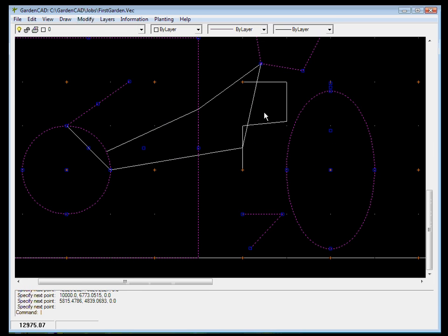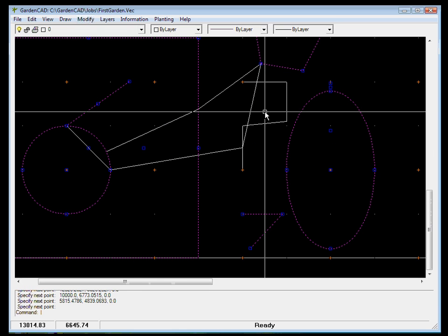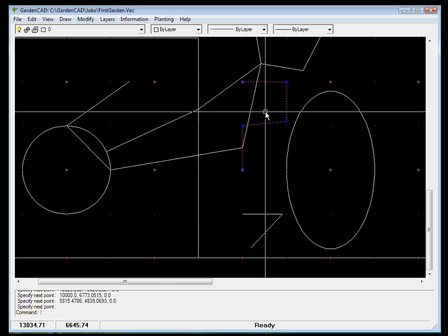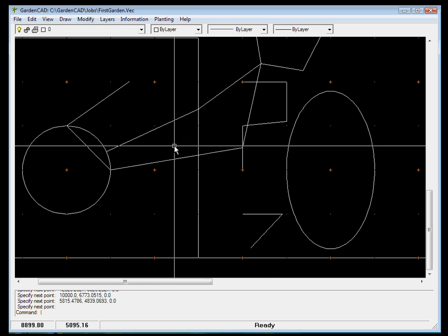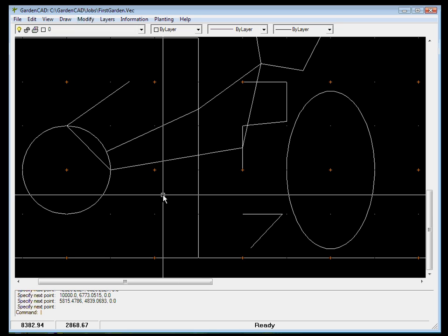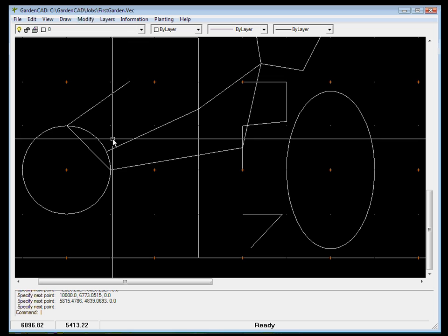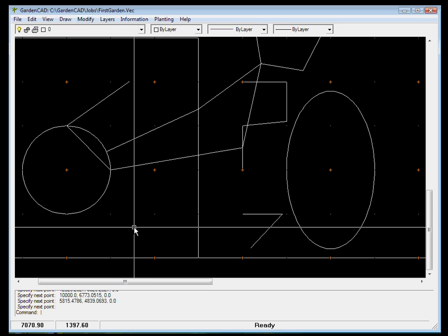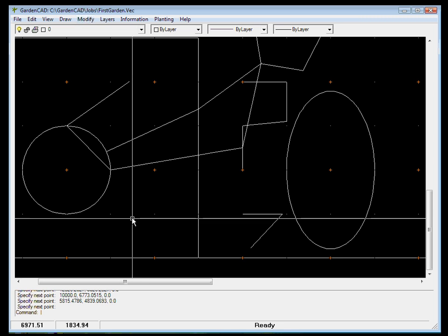This is a polyline. To clear those grips you hit the escape key. Here's a polyline, which is one single line segment. So every entity in a drawing has got these grips on it, and we can use them to latch onto geometric points in the drawing, as we've been doing when we were drawing those lines. So it's a very useful technique indeed.